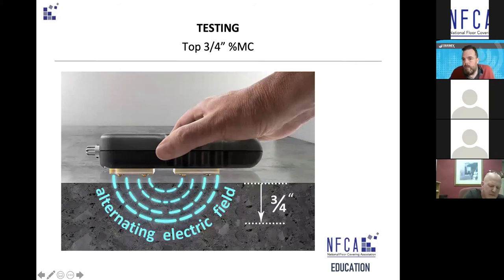So if you think about it, we supply moisture equipment to the roofing industry, the flooring industry, the EIFS, which is external insulation, all around the building envelope. They use meters, and they always do the same thing. There's usually 2 tests that are done together. So for anyone that's familiar with water damage, the water damage industry, the 2 tests are the pin meter and the non-destructive. So they basically use one to record numbers, and they do the other one to map the moisture condition. So it's something similar.